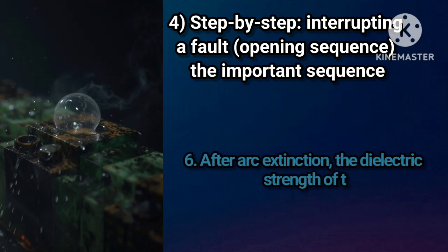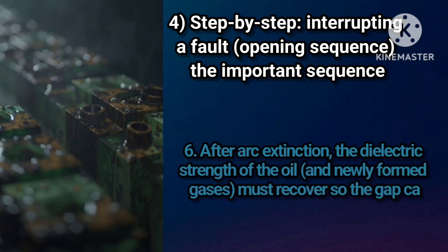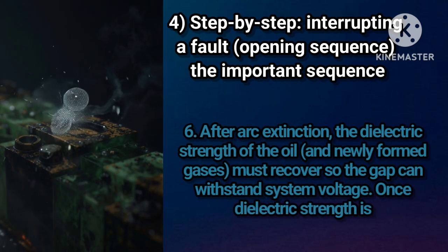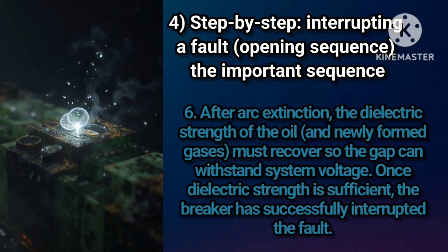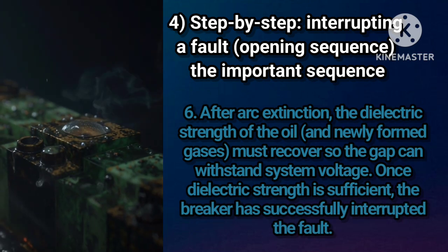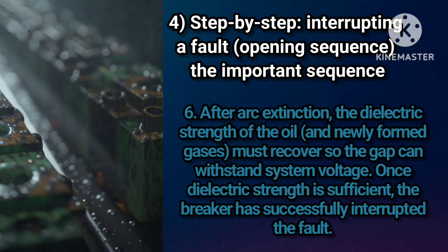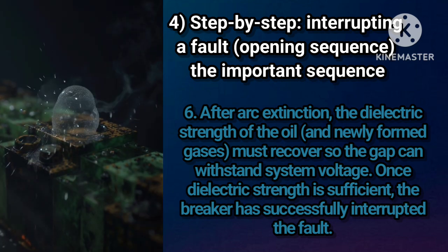6. After arc extinction, the dielectric strength of the oil and newly formed gases must recover so the gap can withstand system voltage. Once dielectric strength is sufficient, the breaker has successfully interrupted the fault.